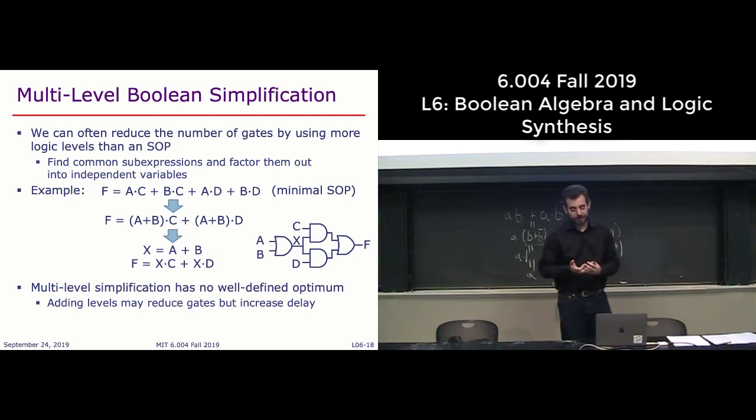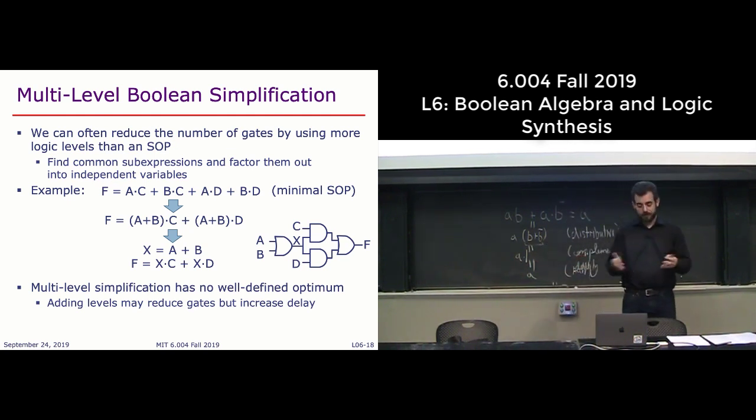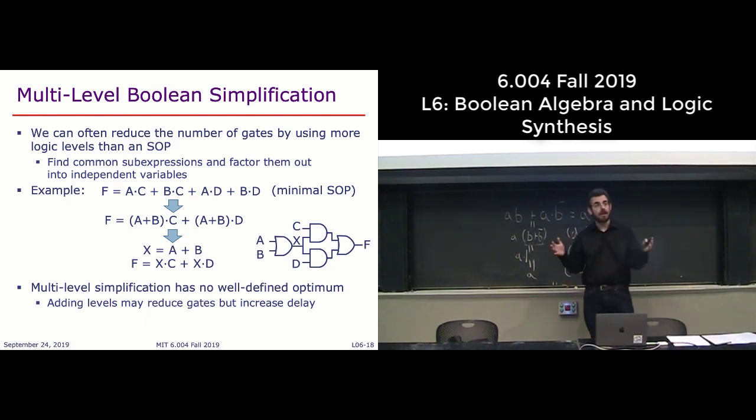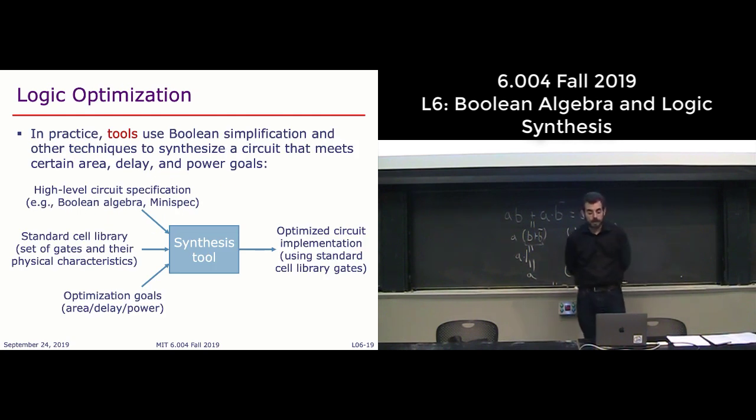Sometimes you end up with hard area versus delay trade-offs, right? You're going to have something that is going to give you very low delay, but it's going to have a large amount of area, lots of gates being used for it, or fewer gates but more delay. So in practice, we're not going to do this full-blown optimization manually because it is a really, really hard optimization problem. And so in practice, we're going to use synthesis tools.